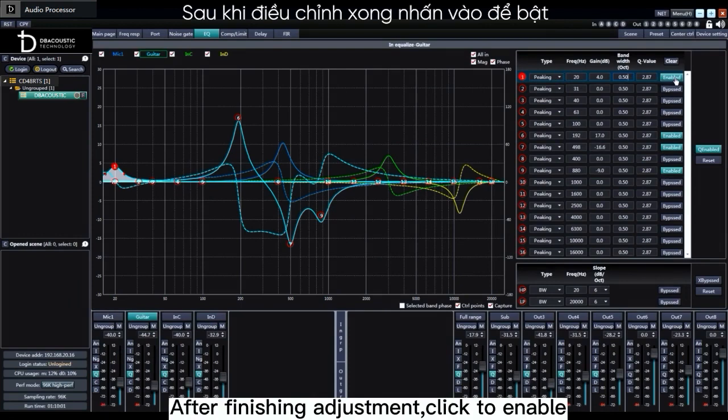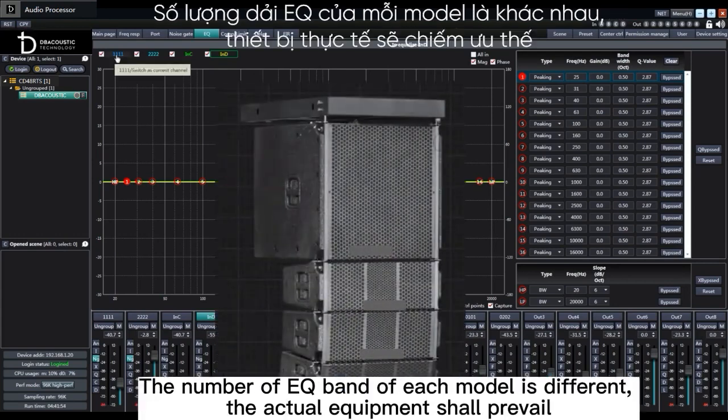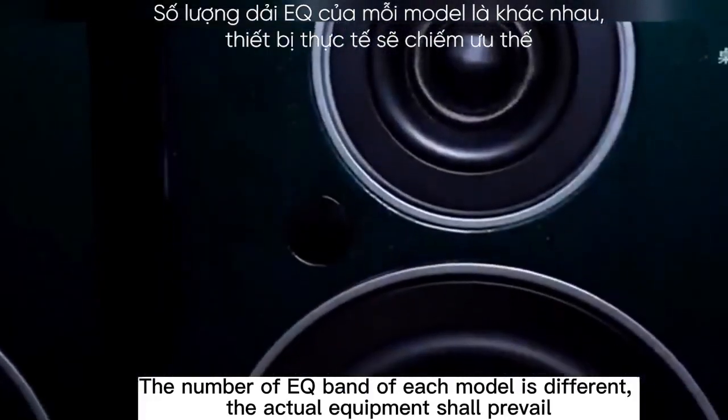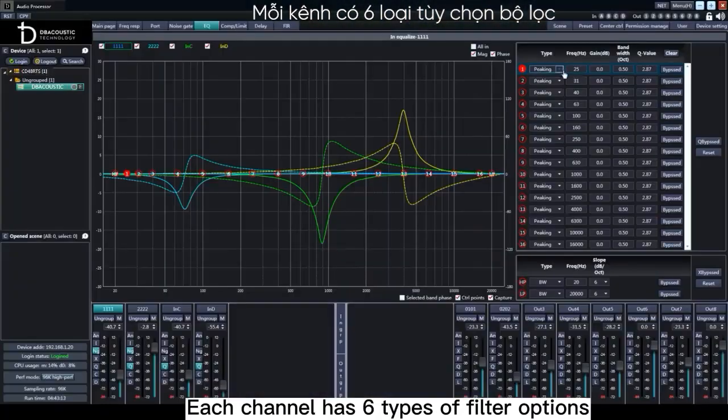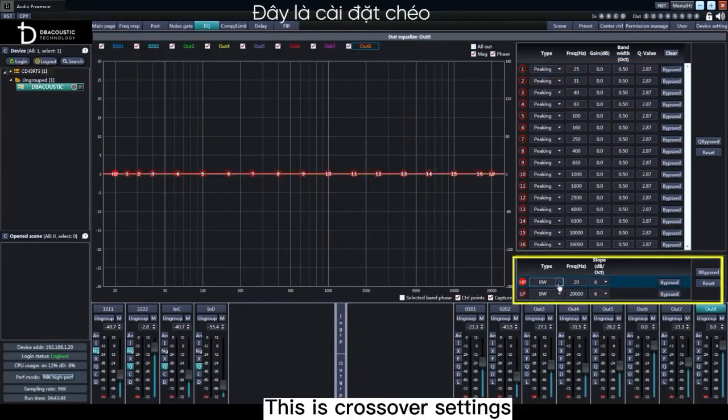After finishing the adjustment, click to enable multiple band EQ for each input and output channel. The number of EQ band of each model is different. The actual equipment shall prevail. Each channel has 6 types of filter options: peaking, notch, the first all pass, the second all pass, high shelf and low shelf. This is crossover settings.